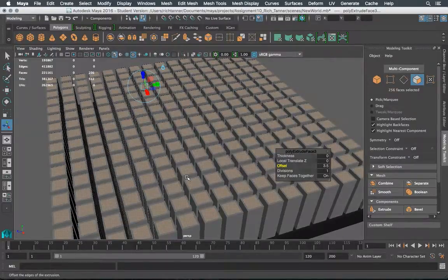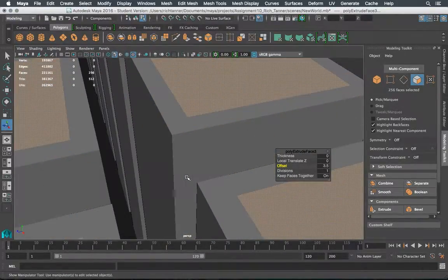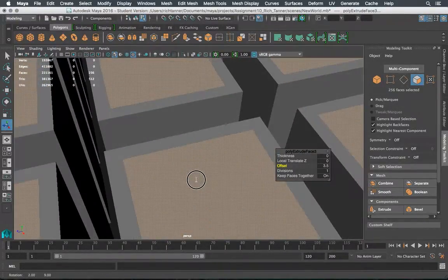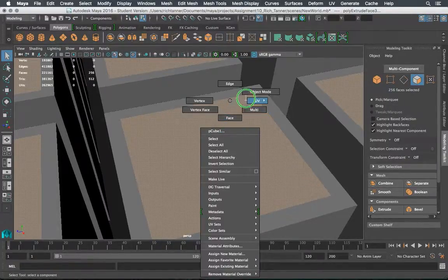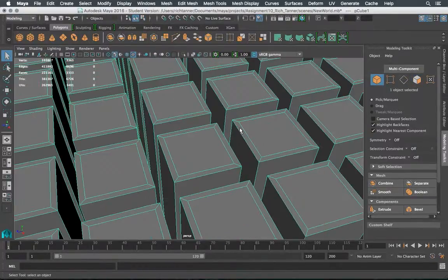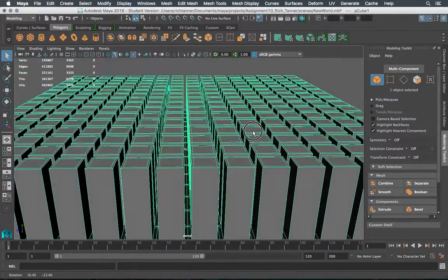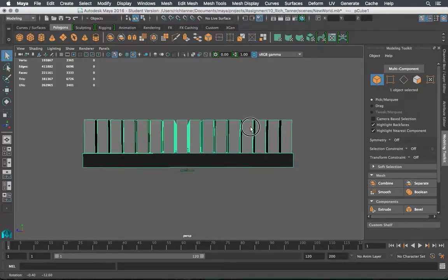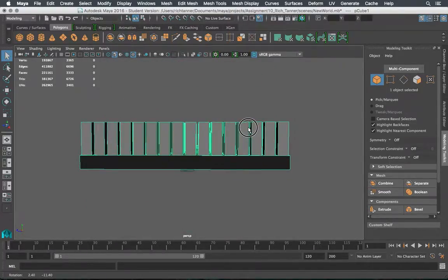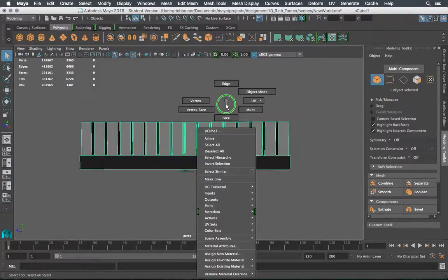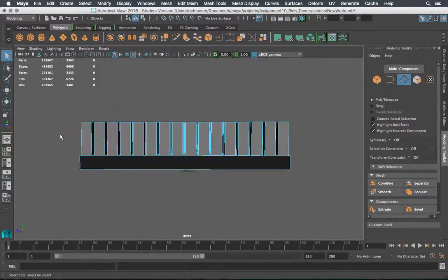I'm going to inset that. So let's go in. Those are pretty thick sidewalks. Let's go with 3. That's a good size sidewalk. All right, we'll leave that as is. And the sidewalks are way too high because we're going to get fancy with them before we put them back down. So I'm going to go to edges.